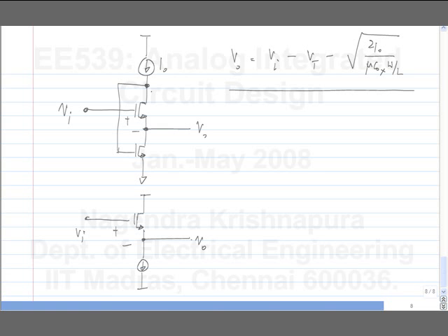Okay. So what does it do? That is fine. That's some detail, right? Because the way we bias, here we sense the current at the drain, here we sense it at the source. That's why the current source is on top, here it's at the bottom. Okay. And that is why here the drain is grounded, there it is not. That's fine. But besides that, as far as the characteristics of the common source amplifier is concerned, swing, okay. Even more basic characteristics. Even you have it here also, right?